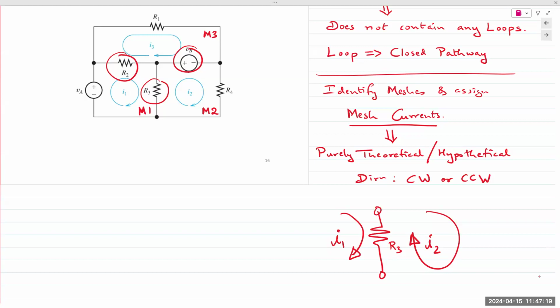That means you have one current going up, one current going down, or left and right, which is physically impossible. Current through a resistor would only flow if the two points are at two different levels. If both ends of the resistor are exactly the same electric potential, then the voltage across those 2 points is equal to 0 volts. One end of the resistor has to be higher for current to flow. Current always goes from high to low, right?